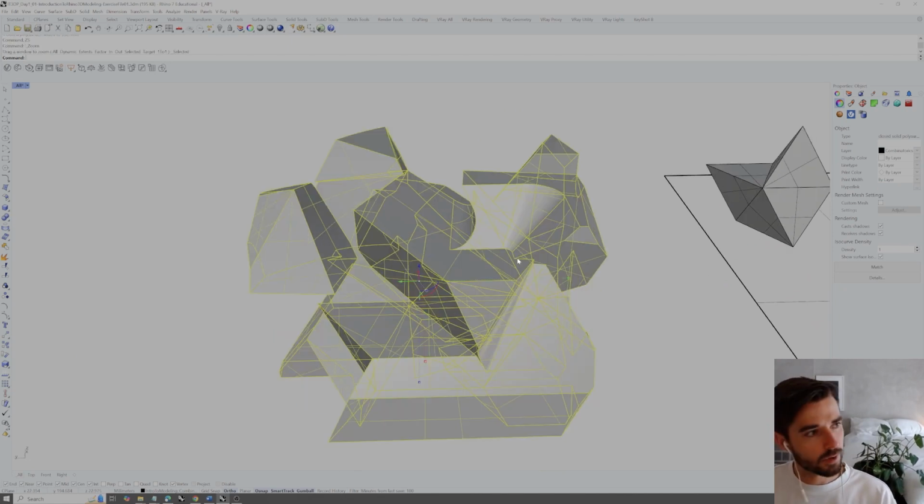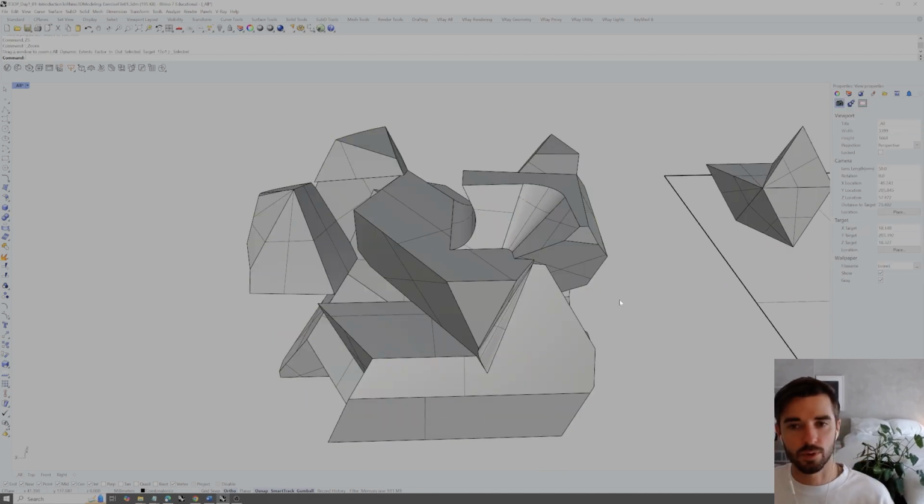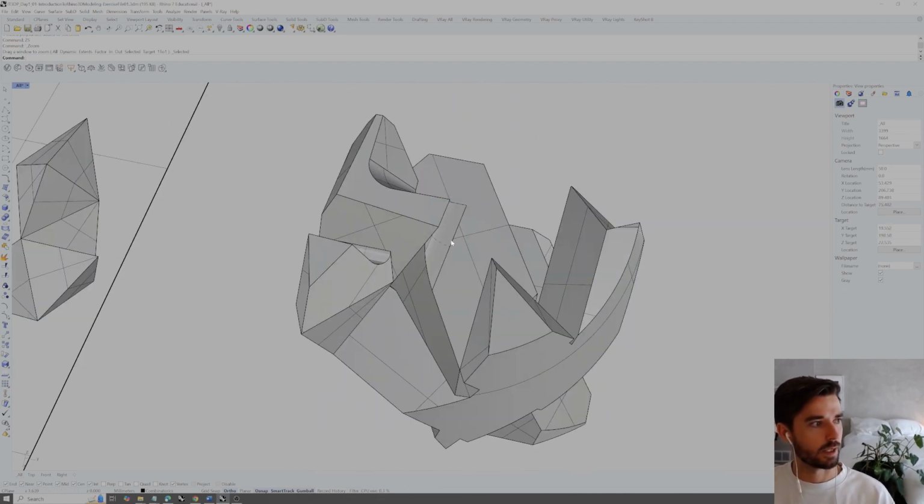So if you ever get into trouble with the Fillet Edge tool, that's the same kind of operation that you need to go through. First, analyzing what the issue is, and then going step by step through and extracting faces or surfaces, drawing out new planes, splitting, getting intersections between them, and then trimming the radius and trimming the planes so that you can create one new clean intersection.